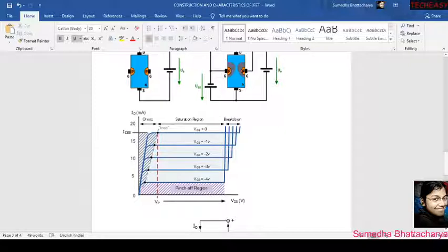And in that case, if after VGS is applied, you connect the VDD, then you can see that with giving a very low or very slight voltage, you can find the pinch-off voltage very early. Okay, this is the main difference here.